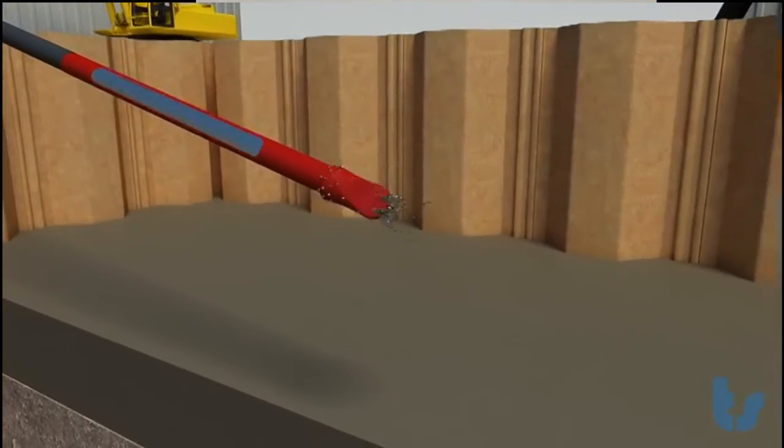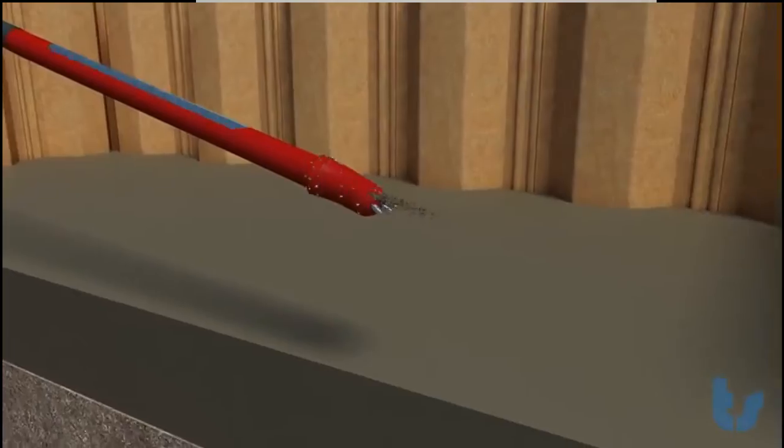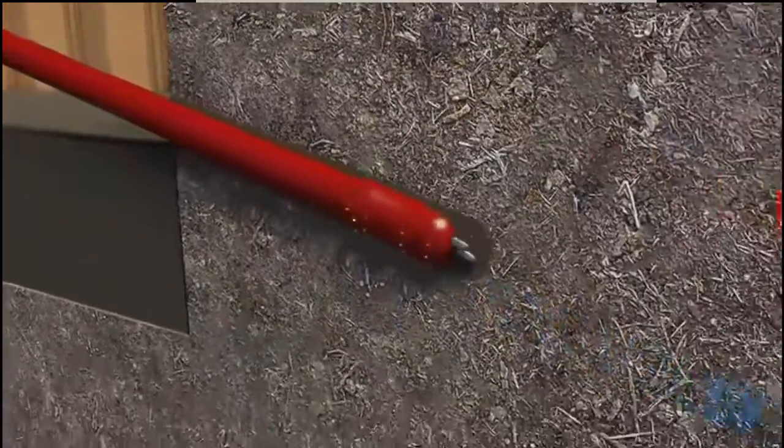They're starting to drill. They're drilling into a pit. That pit is to recover the mud that I said comes back when I'm drilling, through the annulus. It comes back into this pit here. They capture that mud, put it through sieves and screeners, take the cuttings out, and reuse the mud back in the ground again.